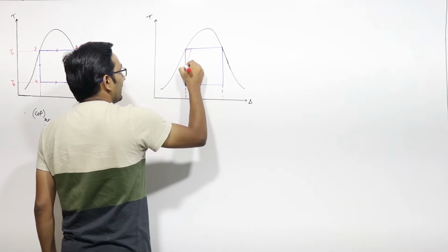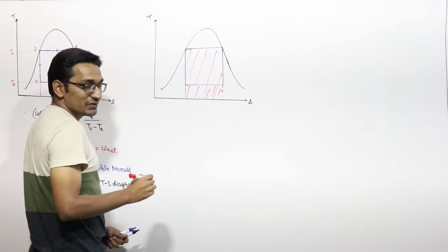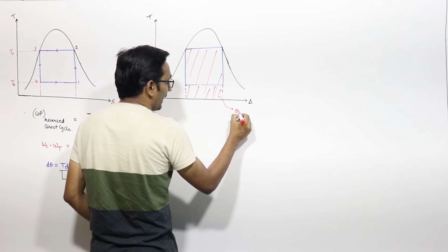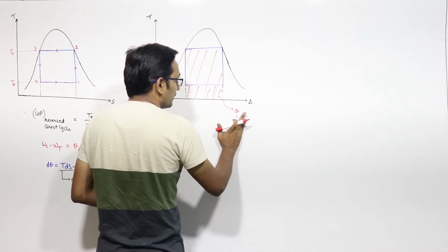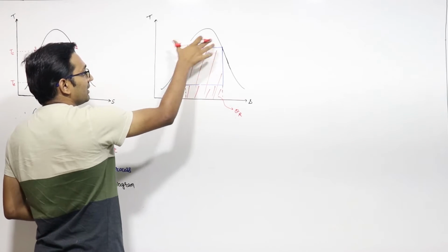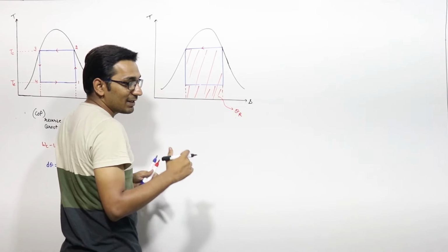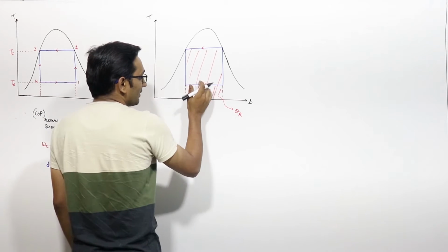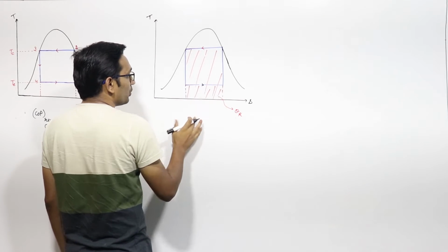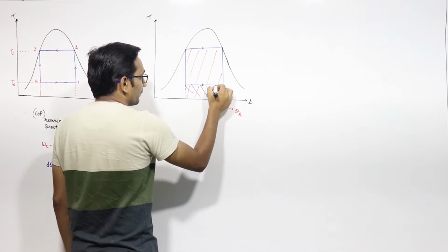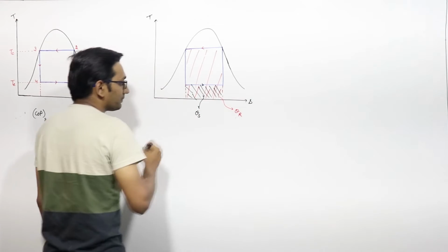this complete area is giving us the heat rejected. What is the heat rejected in this condenser, in this process? And if we talk about the heat supply, or heat absorbed during the evaporation process, then the area under this 4 to 1 curve, this black shaded area, is the heat supply.